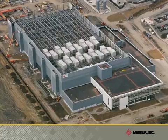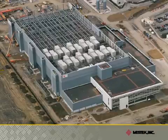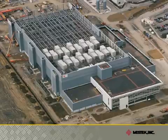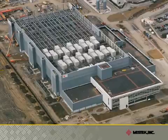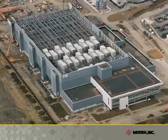And this is the result. This new data center is going to have so many very large pieces of packaged rooftop equipment that there is barely any need for roof at all, and the power consumption will be huge. Even if some of these units may be offline at any particular time, the local electric utility must plan to provide sufficient service from at least 2 independent points, by the way, to meet the total demand of the building. That could mean 50, 100, 200 megawatts of demand load on their grid.